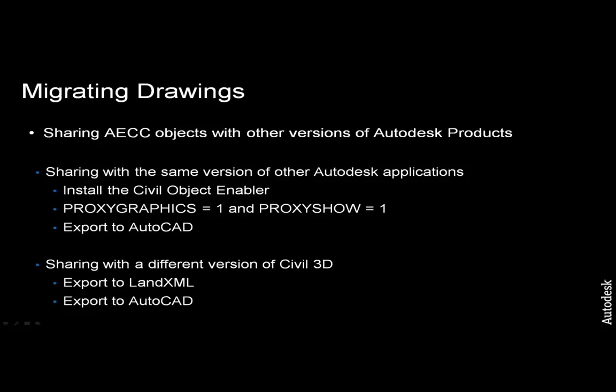However, there are some techniques for sharing AEC objects between one version and another for AutoCAD products. If you are sharing with another Autodesk application of the same version, it is best to use the Civil Object Enabler. This will allow you to open the drawing in the other Autodesk application and see, select, and report on the civil objects in that drawing.